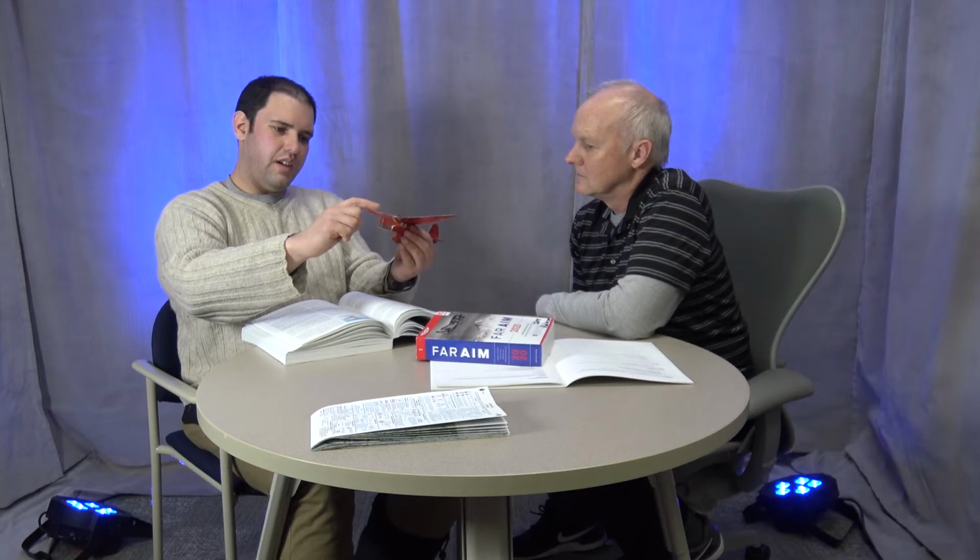Exactly. And then the other thing that's happening as the propeller is spinning, it twists the air. We call the air moving past the airplane the slipstream, and it twists. So as the propeller acts on the air, it'll push the air down on the left side and up on the right side.